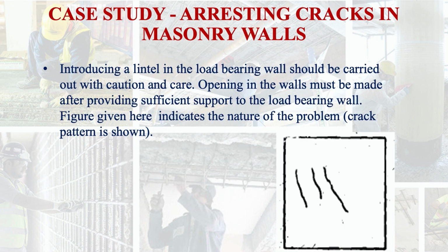Introducing a lintel in the load bearing wall should be carried out with caution and care. Opening in the walls must be made after providing sufficient support to the load bearing wall. Here in the figure, you see the nature of the problem, means the crack pattern is shown here.